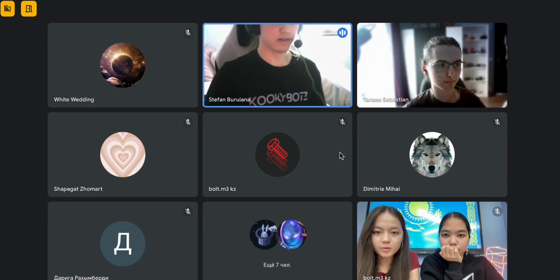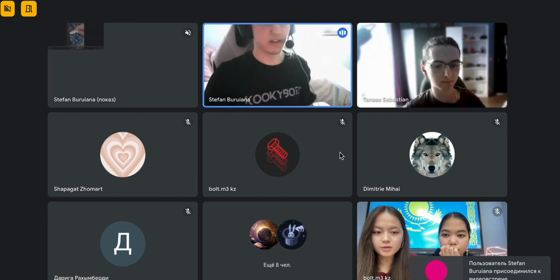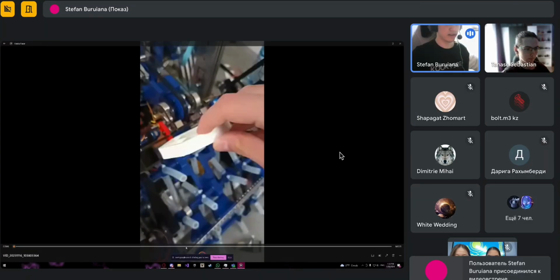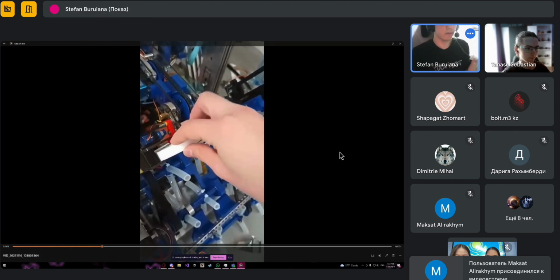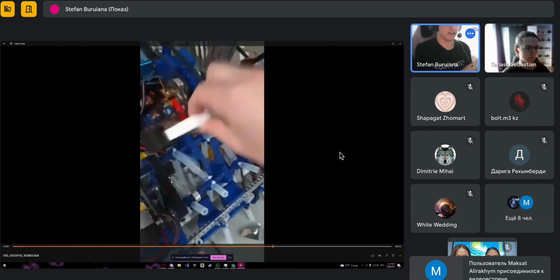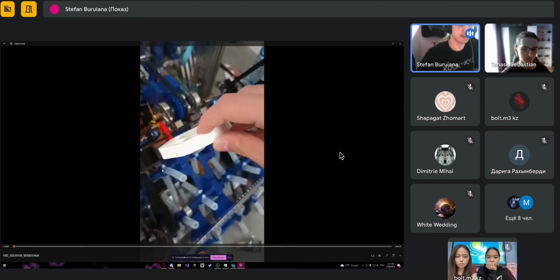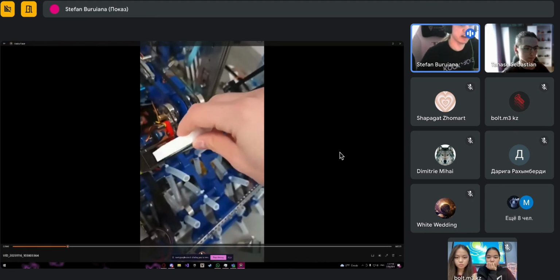Okay. So I think this is pretty hard to see on the actual robot, but we have a pretty close video of this. This is our one-way latch we use on our outtake. It lets the pixels enter the deposit box without putting any kind of strain on the micro servos. Of course, we do still open them because it causes a very specific kind of jam that is pretty annoying. But the benefit of this is that it puts very little strain on the micro servos.